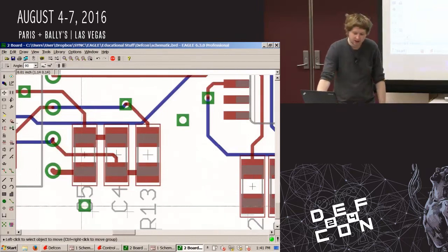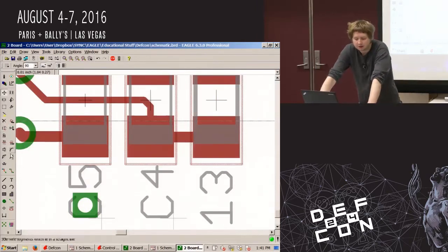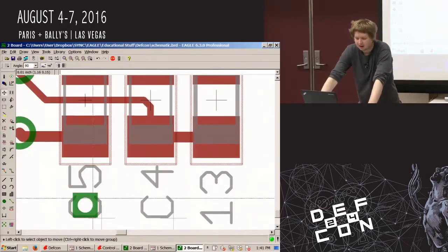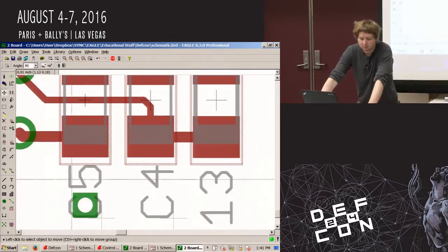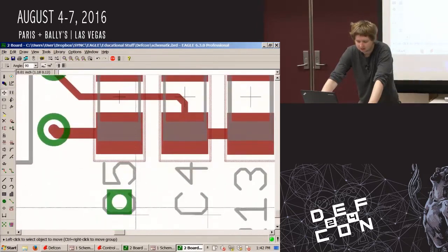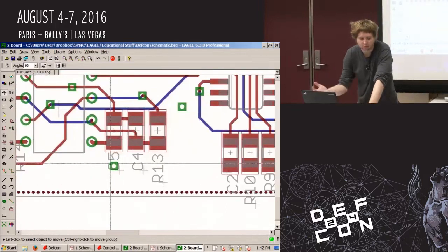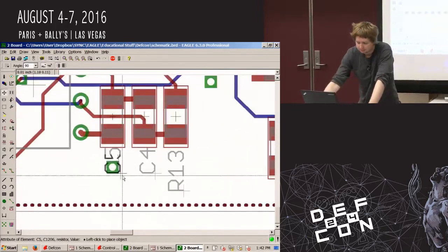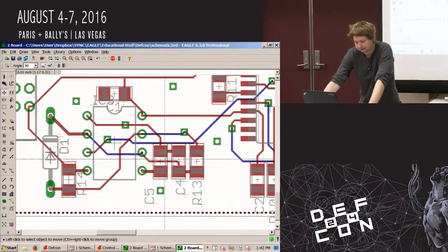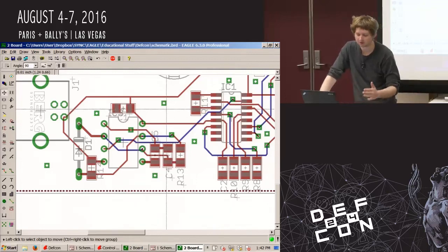Now in this case, I have a via that's going through my reference designator. If there's nothing you can do about it, then it's permissible, but it'd be hard to see which component that actually is when you really only have a 5. If you have the original source file, then it's not a big deal. You just have the source file open as you're doing your layout. But in this case, I can move it here. I can also move it right here. That'll show up just fine, because in this case, I will have a white silk screen on top of a purple solder mask.